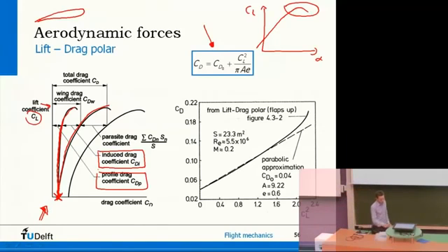So if you look at the whole aircraft, the actual drag-lift relationship looks the same, but the whole curve has shifted to the right, simply due to the fact that there are all kinds of elements which also create drag, like a landing gear, antennas, fuselage, and so on. So this formula here is basically a representation of that curve.